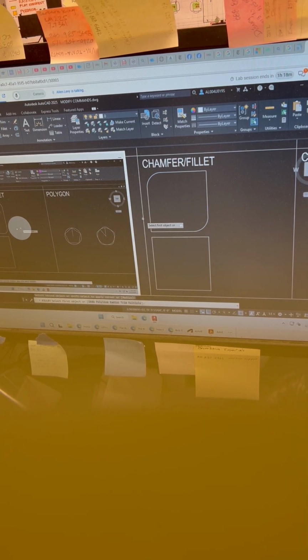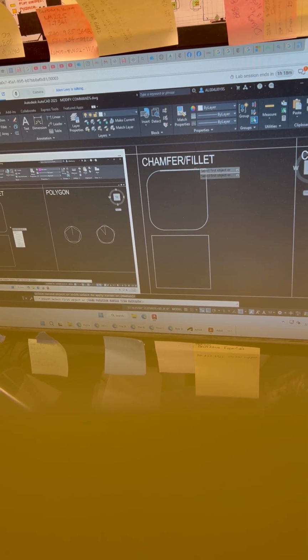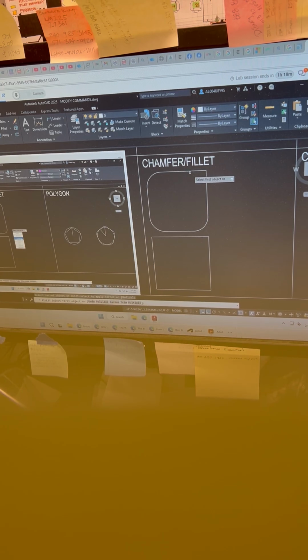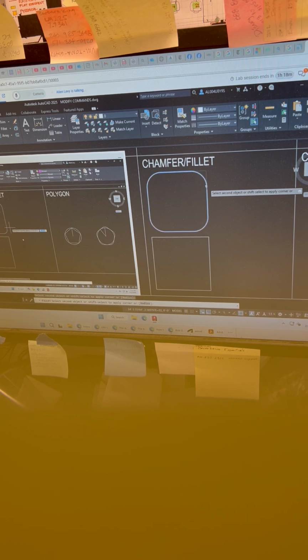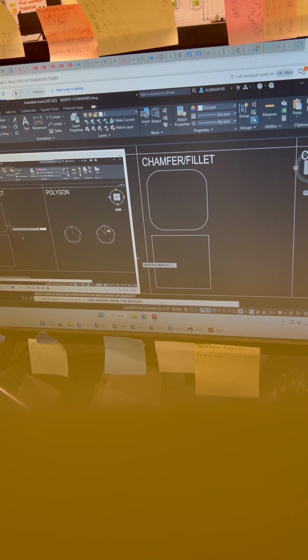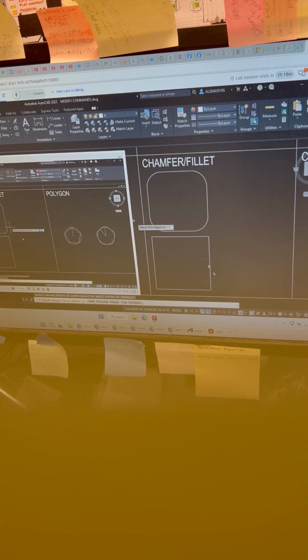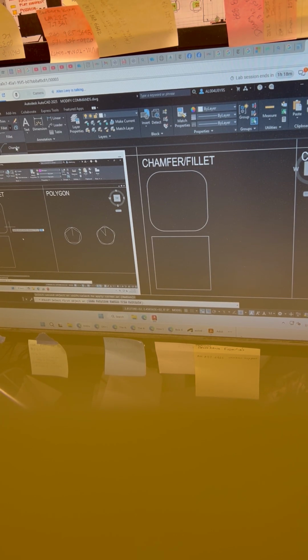Here, this time I haven't done this in a while. I haven't done the down arrow on my keyboard. Down arrow on my keyboard. Distance. Here it is, distance. The first distance, let's make it 12 inches, and go ahead and hit enter. Now, it automatically assumes that we want the second distance to also be 12, but I'm going to make it different.